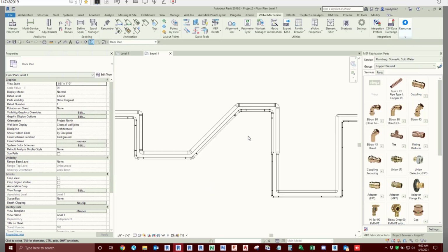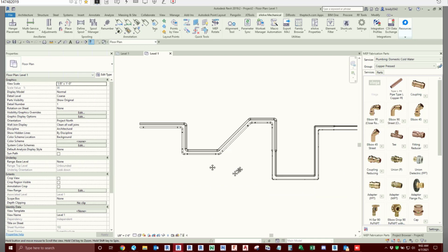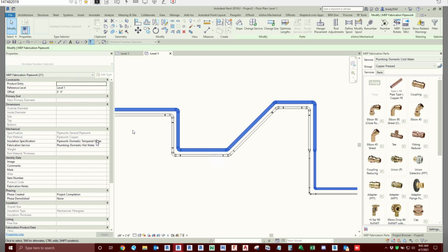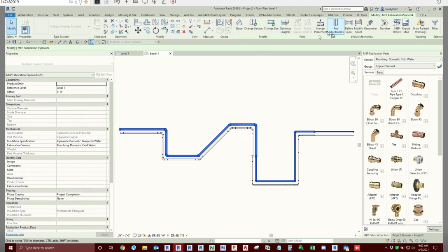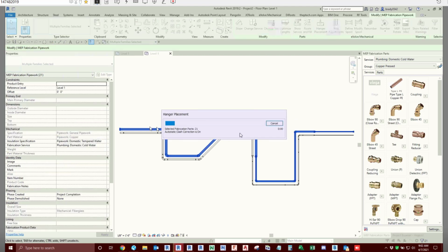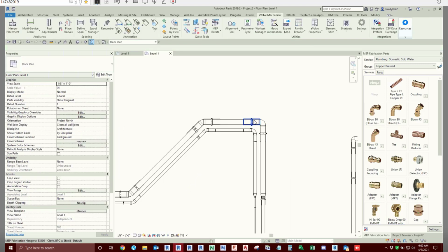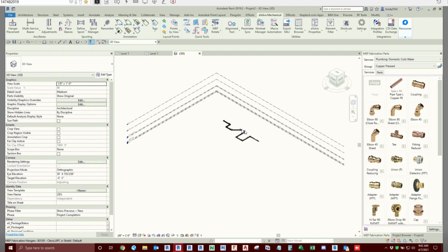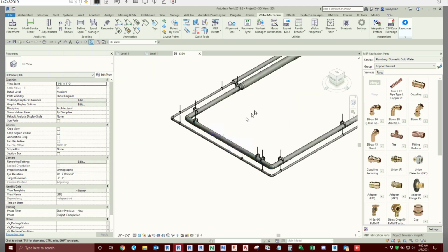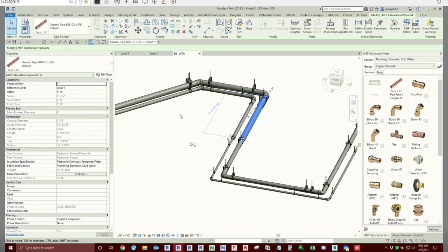You can also see that based on that, we didn't get any hangers put on the hot water system. So I'm just going to switch this back over to cold water, I'm sorry. We'll leave the insulation on there, and then we can add the hangers. And see, there's no errors that came up because it's set in our hanger spec, and it went ahead and added all the hangers with the shields on it. Assuming that we're good to go here, let's look at this in 3D, just because it's super awesome, and it worked pretty well.